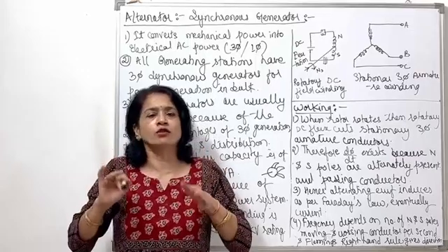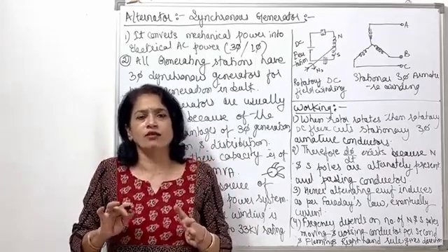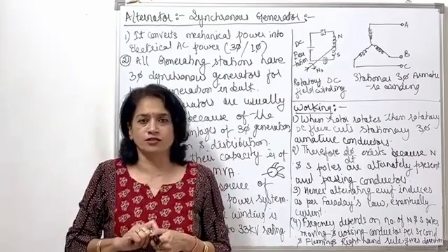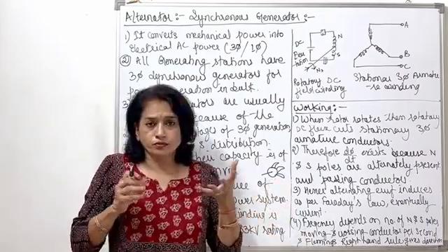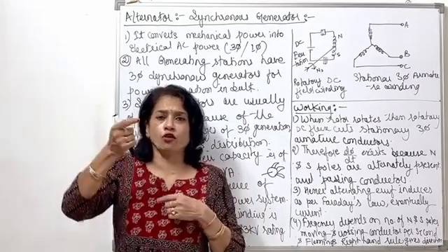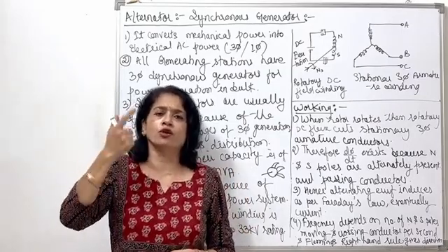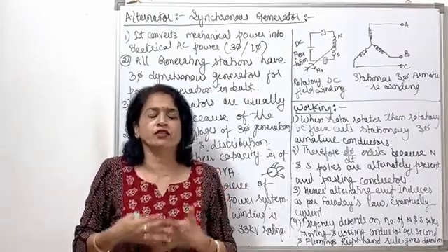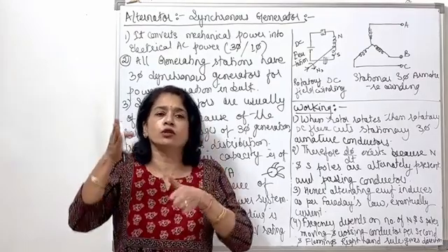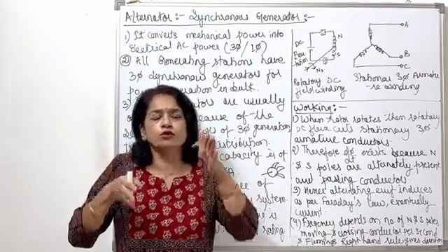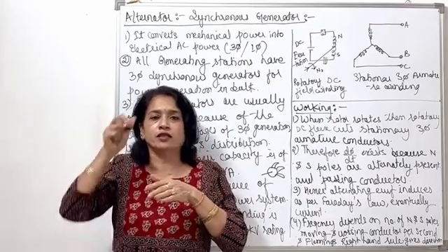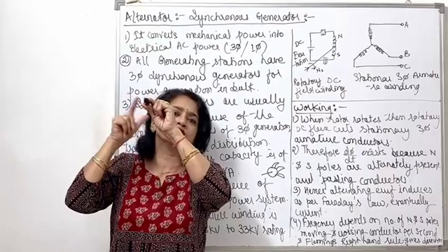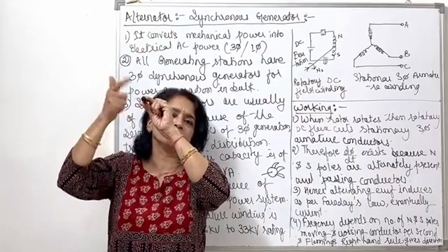So that way we have the three-phase AC power generation as well as alternation of the currents, and three-phase production of EMF. Over which frequency will the alternation of the current's direction, or the polarity reversal, occur? Certainly that frequency depends on the number of poles, north and south pole, which are passing these conductors. The number of poles passing this conductor creates the number of cycles in this conductor, plus minus, plus minus, plus minus.